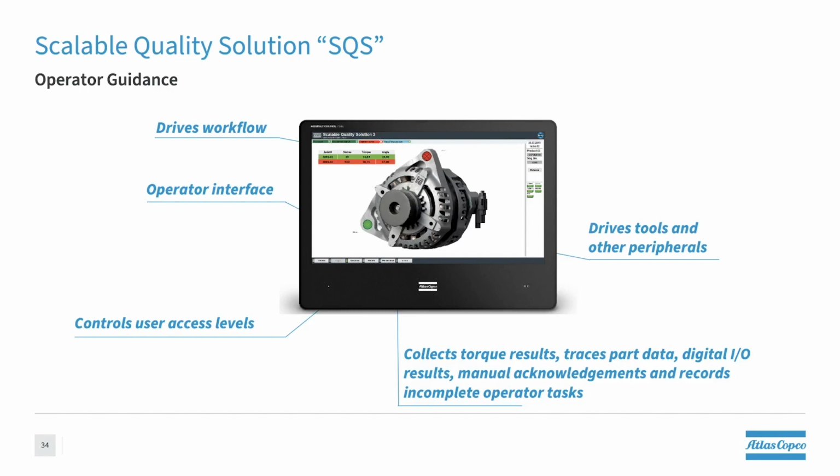Also, like tracking all workflow steps with all connected devices by capturing values, status, and acknowledgments for data analysis and other administration functions. Making sure the operator is trained to work at the station with access control and user identification. Making sure the product is in station, that we're doing the correct build for each unique model, and validating parts are correct before we even run.